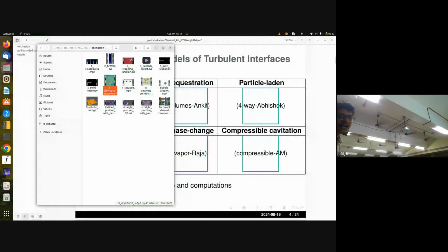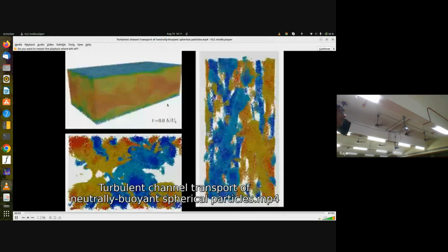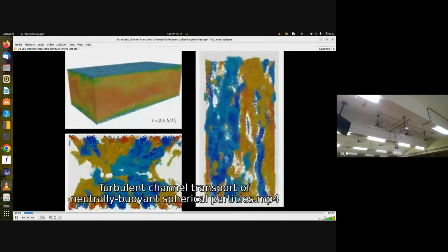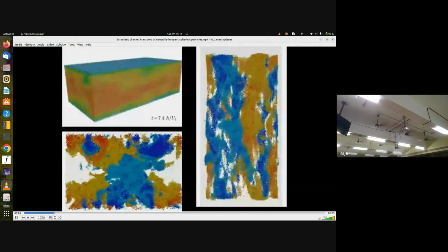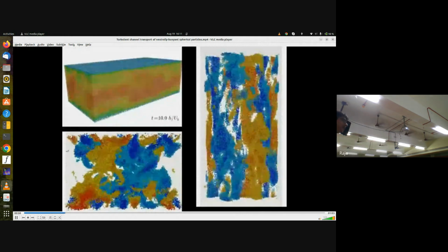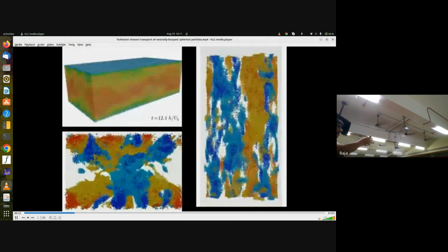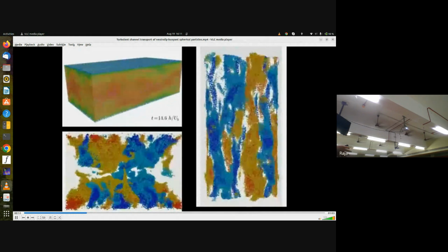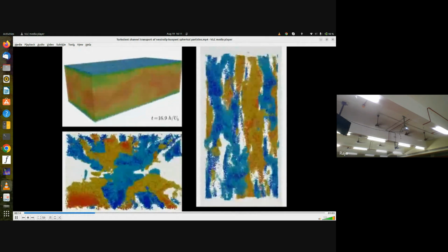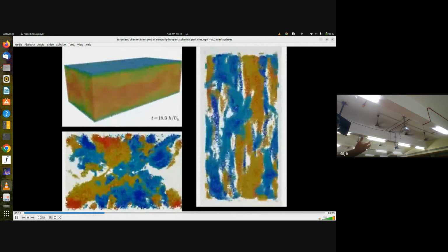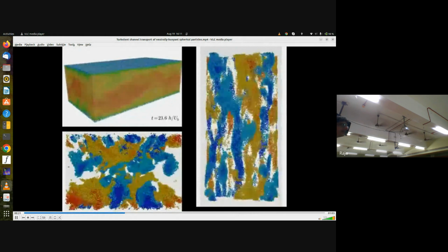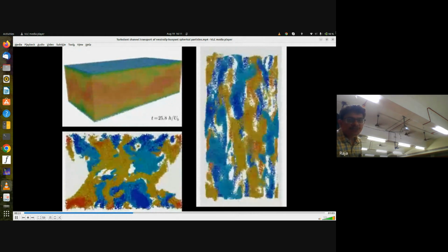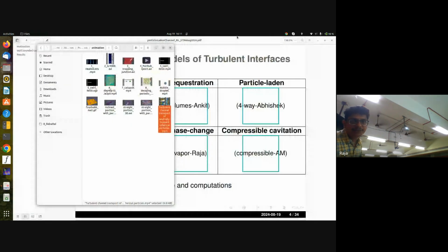In addition to that, we started looking at channel flows where millions of particles are superimposed. The high-speed streaks and low-speed streaks really pull these particles so that they come together like structures, and modify or modulate the turbulence. That is the part of the story we are going to see in today's lecture.